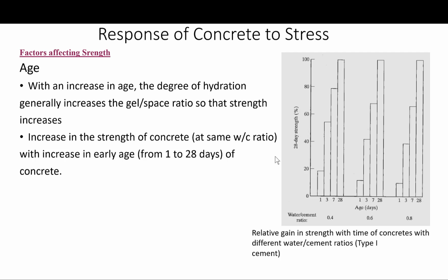So the second factor is age. The rate of strength gain also depends on the initial water cement ratio. With low water cement ratios, mixes gain in strength more rapidly than high water cement ratio mixes, as shown here in this figure. This is due to the fact that strength depends approximately on the cube of the capillary porosity, and because a greater portion of the cement remains unhydrated at the low water cement ratios.